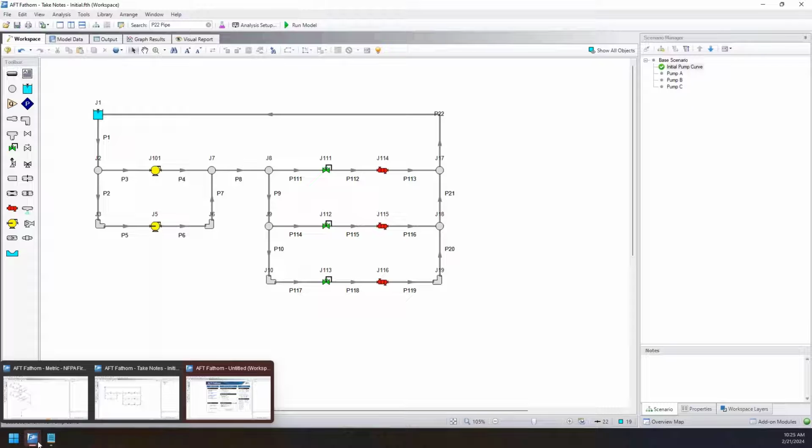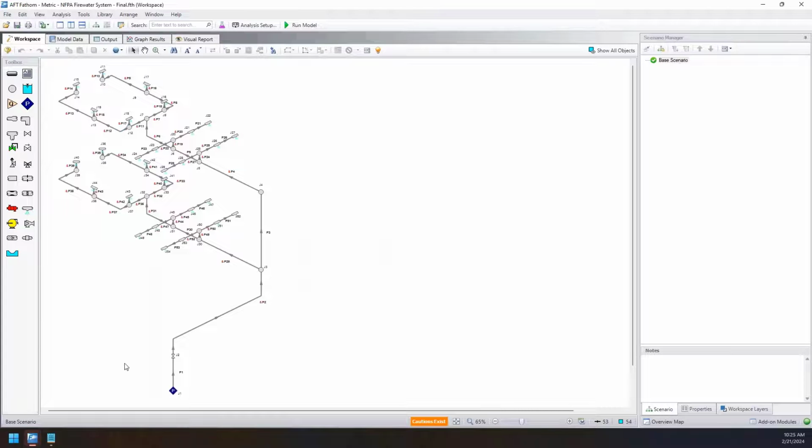Before we go to Select Special, one other selection tool I'll show you is selecting a specific flow path. So let's say that I wanted to show how my pressure is changing from this pressure inlet into my spray system, and as my flow is reduced through all of these different sprays, what does my pressure profile look like along that flow path?